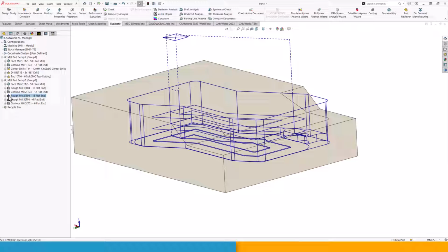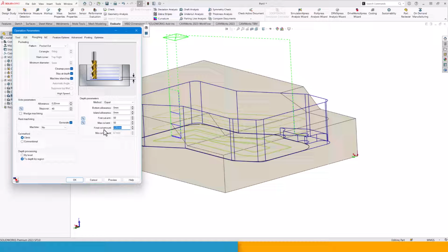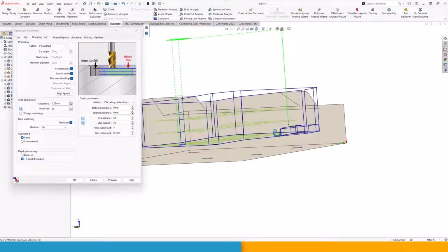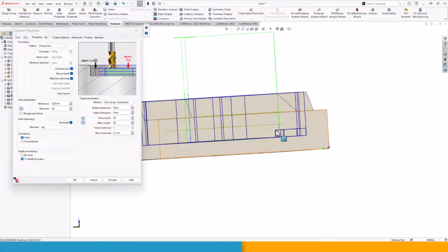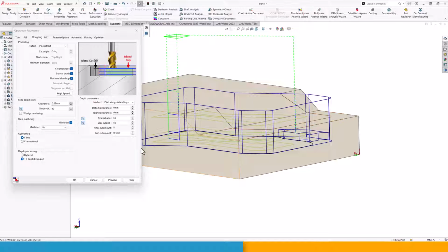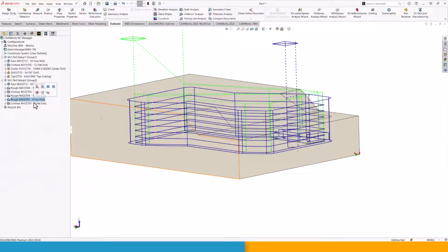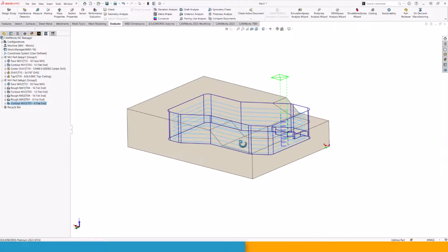and I'm going to make a few adjustments to this one. I don't want to do a finish pass on the bottom. I mean, I could, but I do want to machine either distance along or exact, and then island top. Both of these should generate a toolpath at this layer. So let's see. Yeah, we got that, and everything's good. So perfectly fine. Now that is basically it. I mean, we have programmed this part file, and